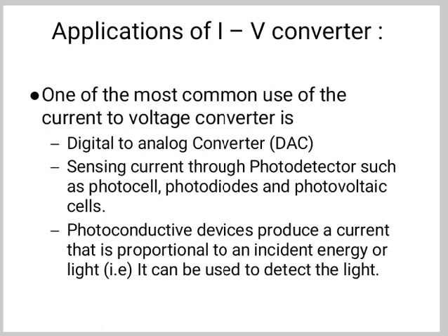Op-amp based transimpedance amplifiers are frequently used to amplify the current signal generated by the photodiode. These implementations are susceptible to oscillations, problems caused by the photodiode junction capacitance, where the photodiode has been replaced by the equivalent circuit.